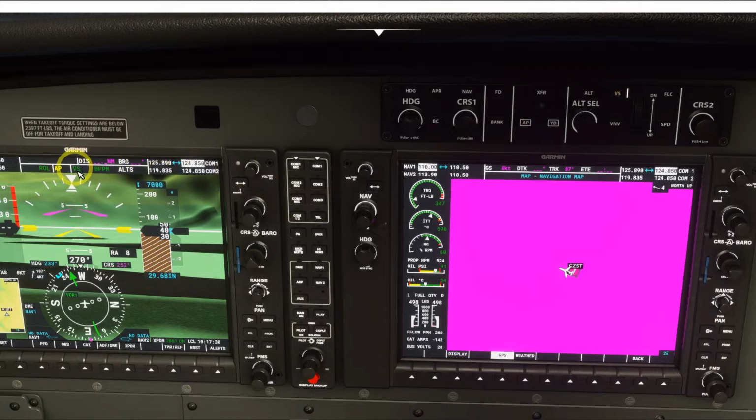You will change here to vertical speed. Right now it's 0 feet per minute, and if you scroll up, you are descending, and the vertical speed bug indicator will change there, and you can scroll up and down to change how much you want to climb or descend, or how fast. So that information will show here, and that's the bug that will follow.